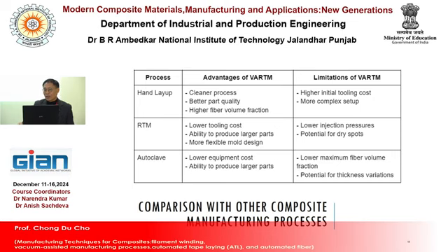And the limitation compared to autoclave is a low maximum fiber volume fraction, because compaction pressure is low, and the potential for thickness variation, which is an inherent weakness.